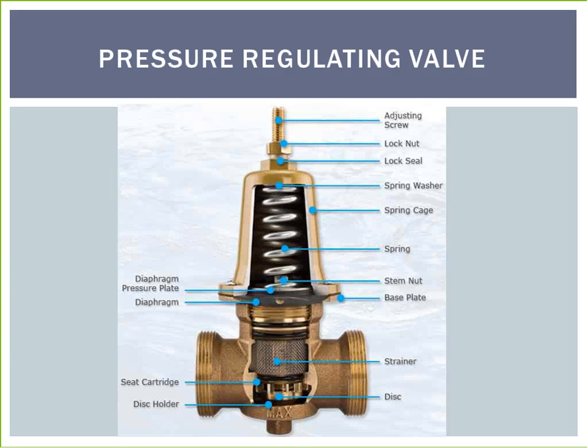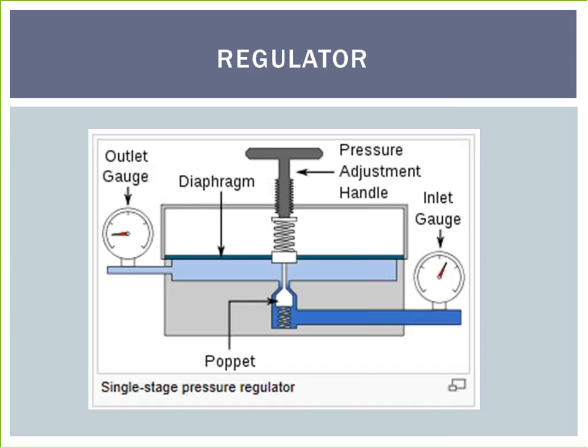A pressure regulator is a valve that automatically cuts off the flow of a liquid or gas at a certain pressure. Regulators are used to allow high-pressure fluid supply lines or tanks to be reduced to safe and/or usable pressures for various applications. Gas pressure regulators are used to regulate the gas pressure and are not appropriate for measuring flow rates. Flow meters, rotameters, or mass flow controllers should be used to accurately regulate gas flow rates.